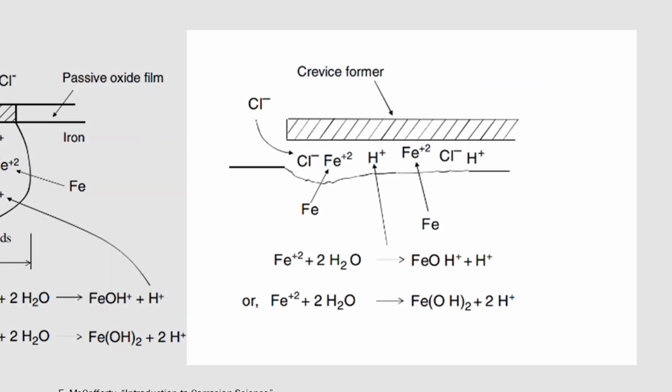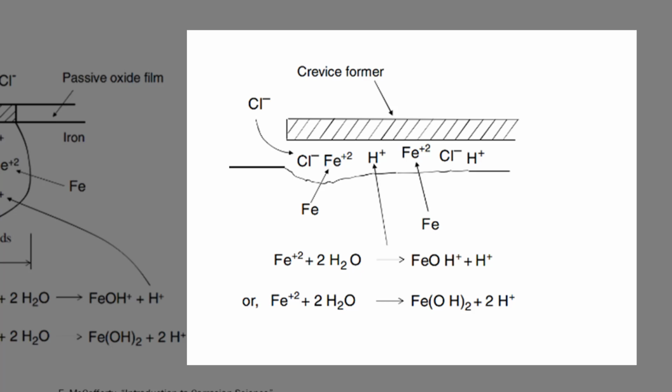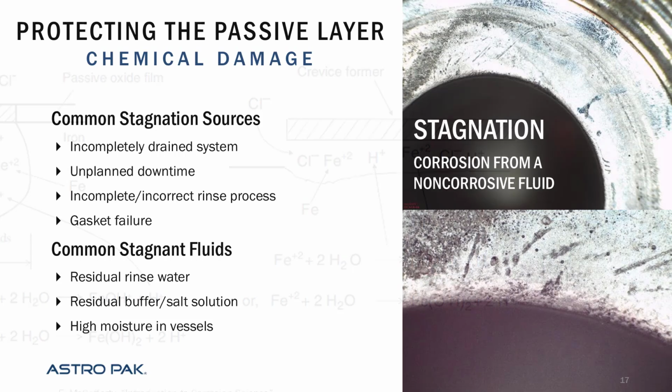On the right is a different form of accelerated corrosion, but it looks so similar. That's crevice corrosion. So it's the physical geometry of your environment lending itself to, or creating, stagnation that results in the same sort of mechanism as a pit. You cannot refresh your electrolyte. Your process flow rate's not going to rinse out all this pH-lowering product that you're making, and you've got accelerated corrosion in an otherwise non-corrosive environment. So I'll talk a little bit more on stagnation.